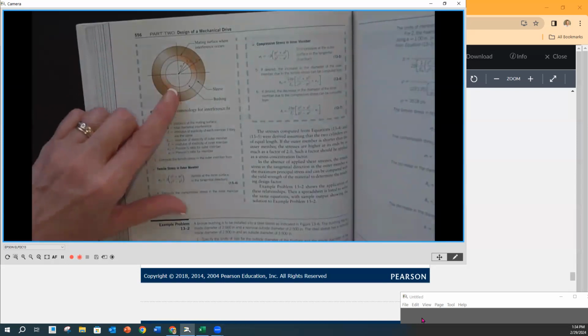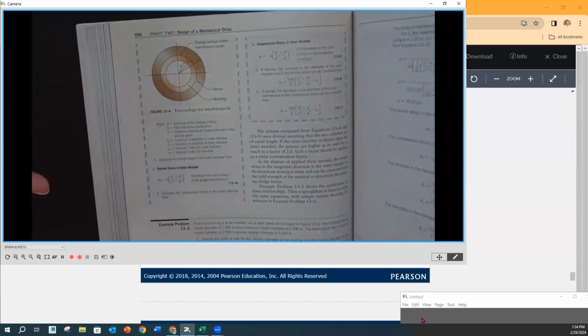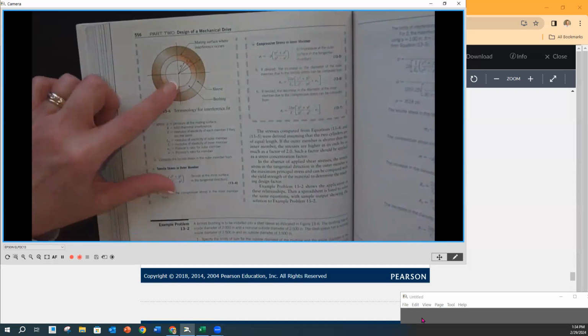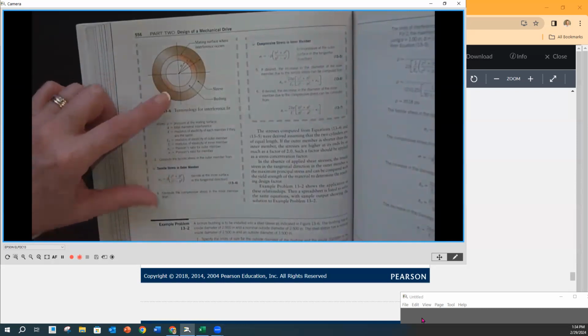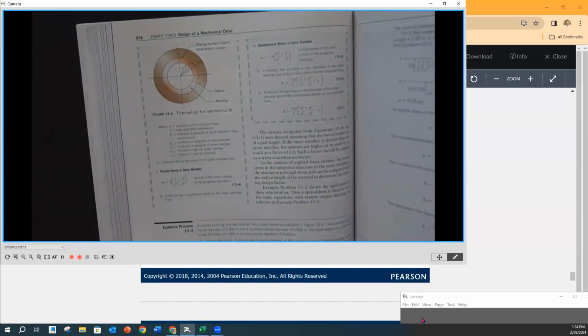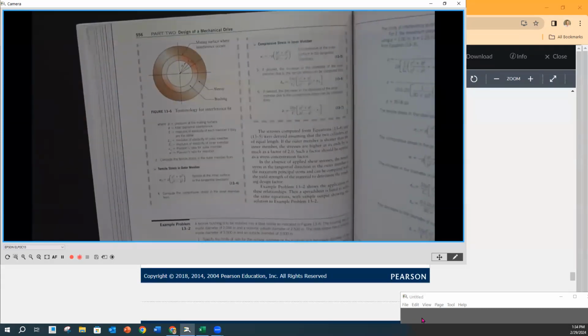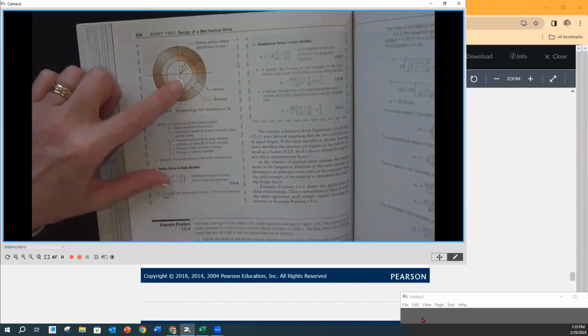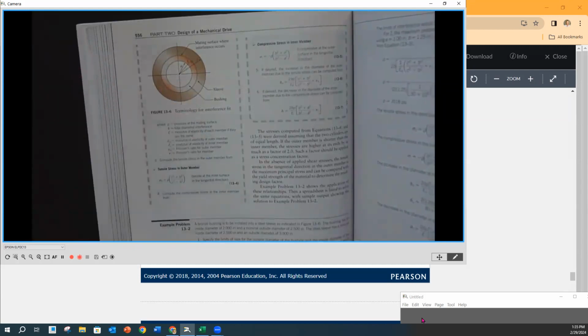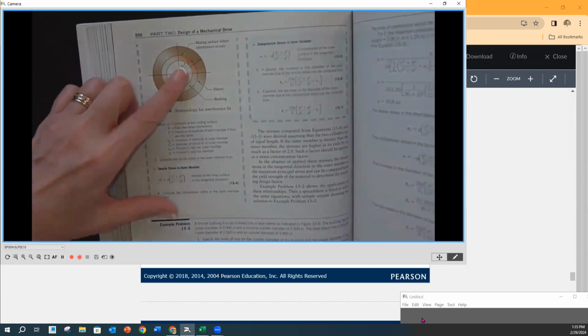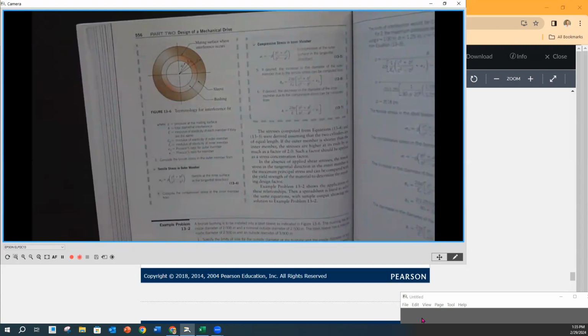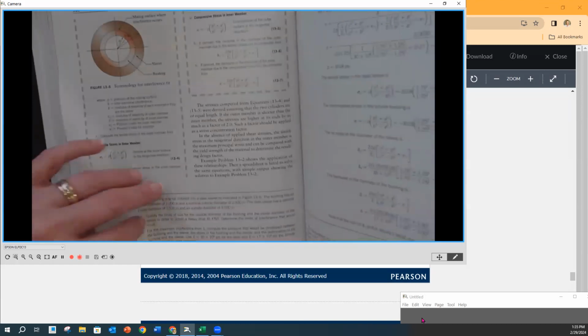Many times these are called bushing on the inside and sleeve on the outside. But this can be any elements. Like I said, we're doing it in terms of round things. This could be a solid shaft where we're going to be pressing on a gear. We could do that. Okay. So it's just really the inner portion is the bushing and the outer is going to be the sleeve, but these can be different types of elements and they don't have to have an inside diameter. If A is solid, then A would be 0 in our calculations. Okay. So these are the radii, the A, B's, and the C's.